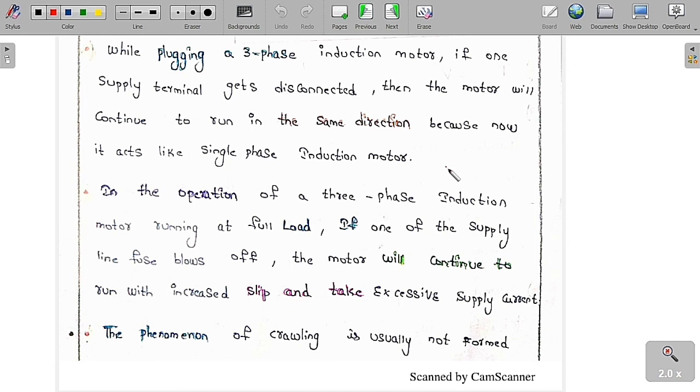I already told you, single phase induction motors are not self-starting. Means if at starting the rotor is at rest, then it can't provide the initial torque. But if it is running, then it can provide the torque because it is always having the RMF. So whenever it moves slightly, either clockwise or anti-clockwise, it is always going to rotate. It is always rotating, but the speed will be somewhat lesser when compared to the previous speed.